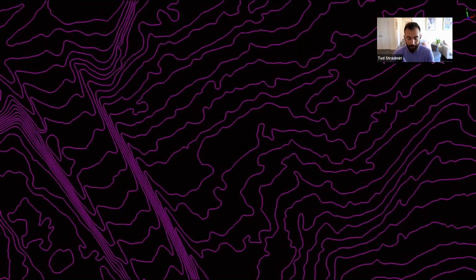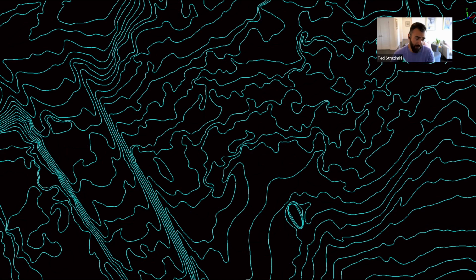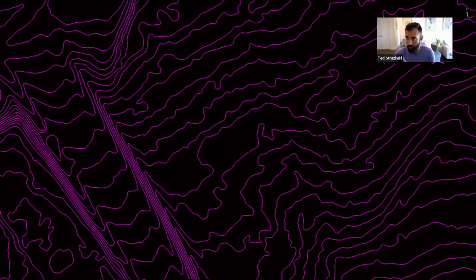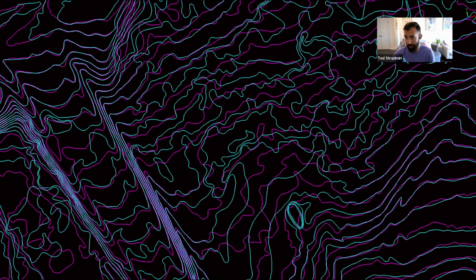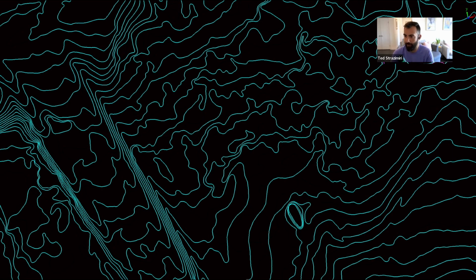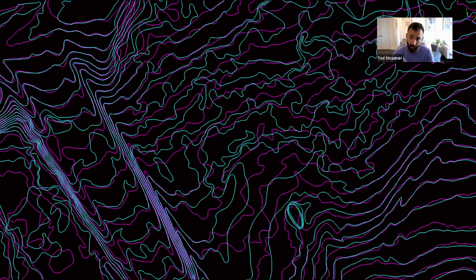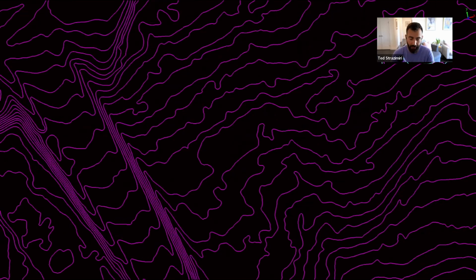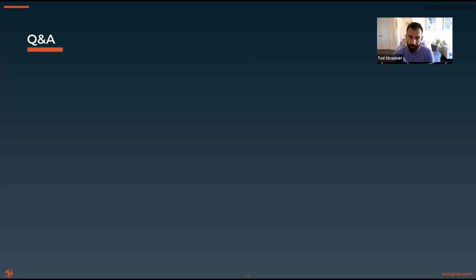The reality is that if you were doing a survey and you wanted the ultimate contours from that roadway, then you should probably use photogrammetry and you should probably plan the mission specifically for that, not a very large area like I was doing here at a centimeter GSD, right? You would want to increase or decrease that GSD in those cases.